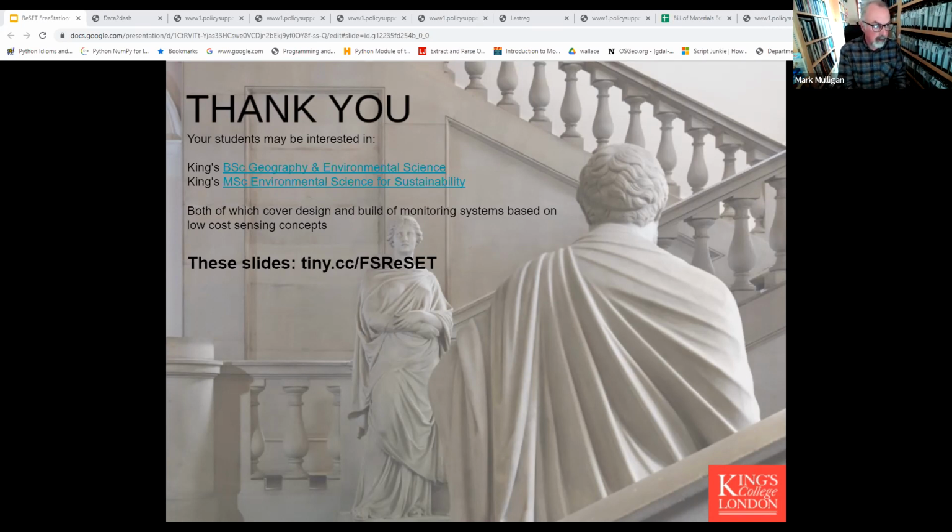And so you would set the sensors to start collecting and sending data at a high temporal frequency, let's say every 10 minutes, but only when the water level is above a certain height, because otherwise you're just draining battery and using phone data costs unnecessarily. So you would use that kind of setup, recording, I would say, at least every 10 minutes, so that you have the capacity to respond.